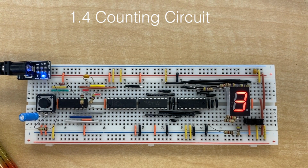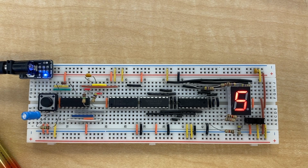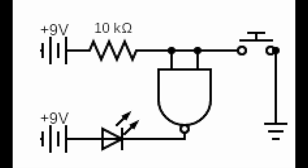This is the counting circuit. It counts from 0 to 9. It starts off with the NAND gate input. When the button is pressed, the NAND gate will produce a high because both inputs are low as current flows straight to ground instead of to the inputs of the NAND gate.